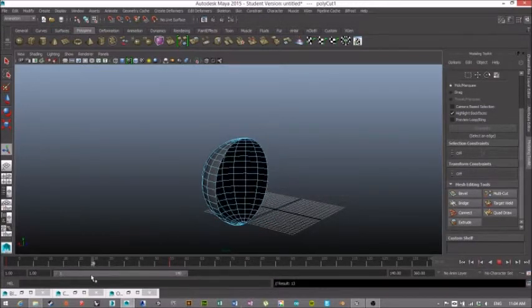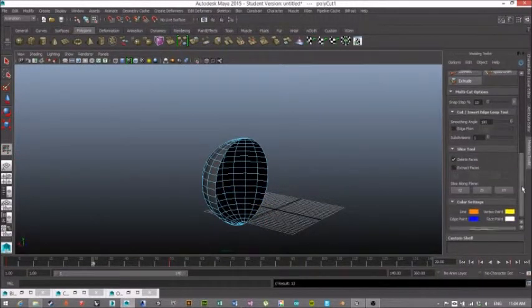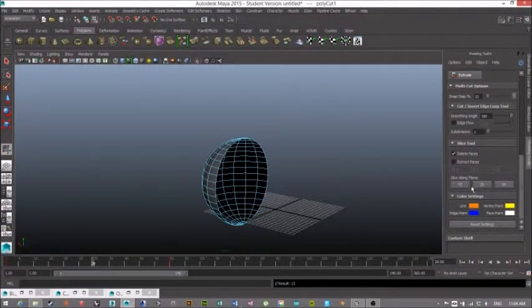And when this dialog box is open here, you just select if you want to get back and do something different. Multicut tool brings up the options for the Multicut tool and change your plane. So we just did YZ. You can similarly do XY, which will cut it this way, and then ZX will give you your plans if you want to do a plan. And sometimes that's really nice. Instead of just having a plan always kind of orthographic, if you have a plan in a perspective view and you then cut through it, you actually can get a lot more information.